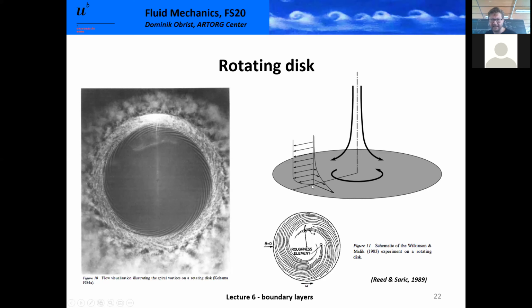Obviously at the wall, we have zero radial velocity, but a high azimuthal velocity. So we have a resulting vector pointing in azimuthal direction, and far away from the disc, the azimuthal component decays to zero, and the radial component goes to its maximum velocity. So the resulting vector is pointing in a radial direction. So it should be clear now that we clearly have a rotating boundary layer.